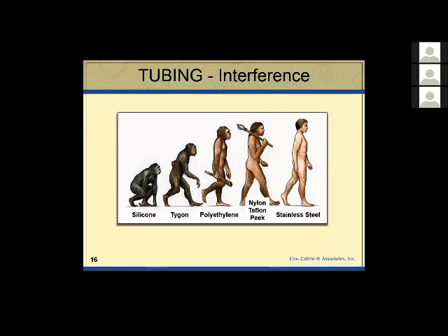Various studies, some show one is better, one is the other, but they all agree that the soft tubing is relatively bad. But it's important to keep in mind the context in which you're using it. We use Tygon on the vapor pins to make connections. We don't use it for long length, certainly not 50 feet, but we'll use maybe a half an inch of Tygon or less to connect our Nylaflow to the vapor pin. The barb fitting where you saw the vacuum gauge was held with Tygon tubing. I've got soil gas only in contact with maybe 5 or 6 millimeters of tubing, not 50 feet. So it's very important when you use a softer tubing, you can do that and you can get valid samples, but don't use any more than you have to.